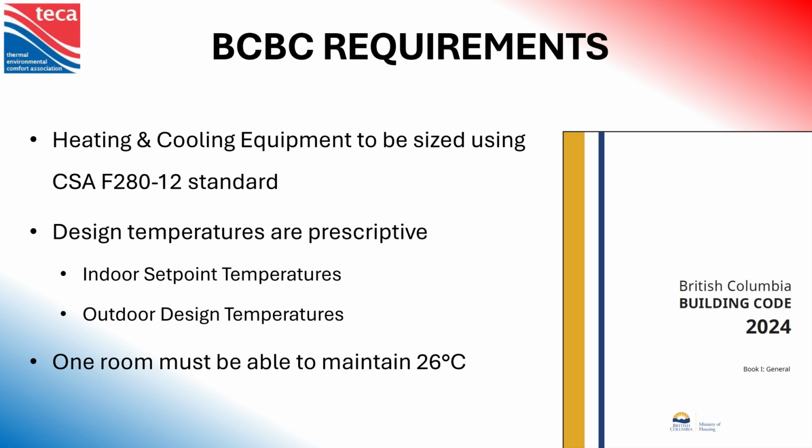The BCBC requirements. Heating and cooling equipment is to be sized using CSA F280 standards. That is the only standard referenced in Part 9 of the code for sizing heating and cooling equipment. The design temperatures are prescriptive, so that's the indoor temperatures and the outdoor temperatures that are to be used. And this is the new clause that's causing a whole bunch of confusion. One room has to be able to maintain 26 degrees C.